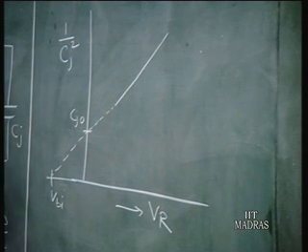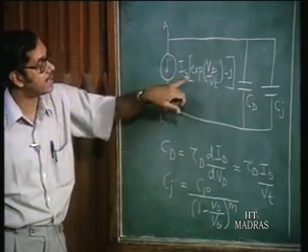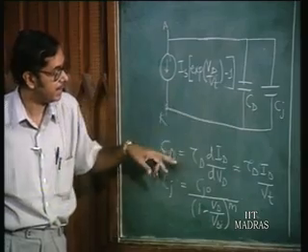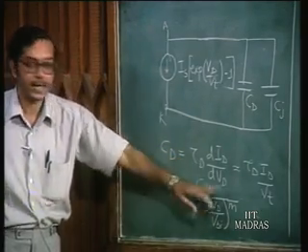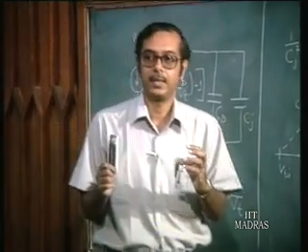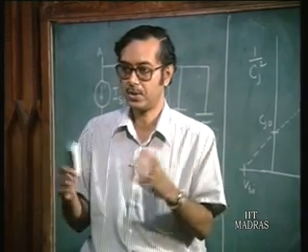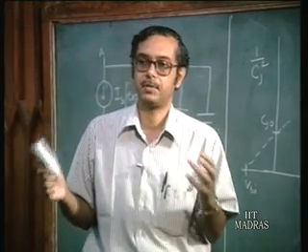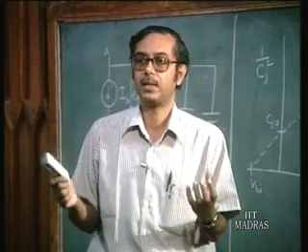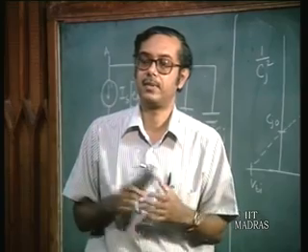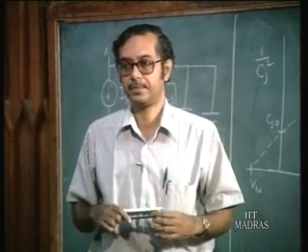Once you know these diode parameters, for example in this case you have Is, the transit time, Cjo, Vbi, m, you have properly defined the different model parameters. Once you know the different model parameters, you can use them properly and simulate the device in a proper fashion. You can use this now to simulate a bigger circuit.